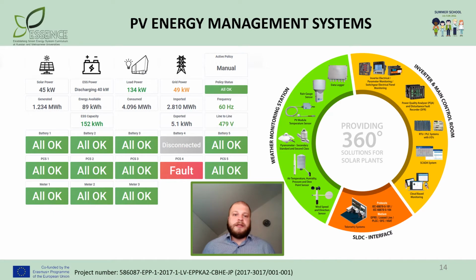And in this slide, you may see the result of how the energy management system for a photovoltaic power plant may look like when we check the states of all of the constituent elements of the PV power plant, like production, battery storage, controlling the load, and controlling the grid connection, where we may see that the power transmission line is disconnected due to the fault.